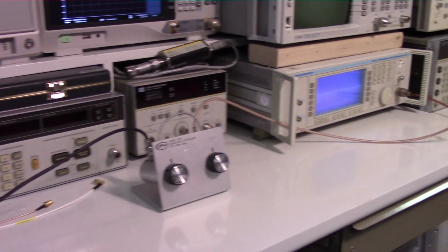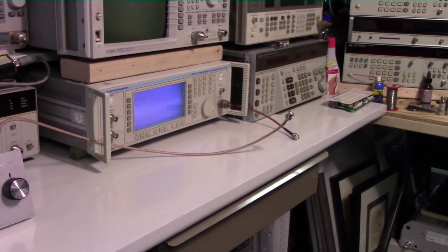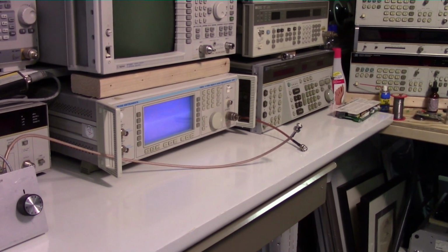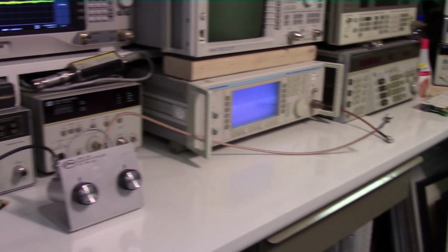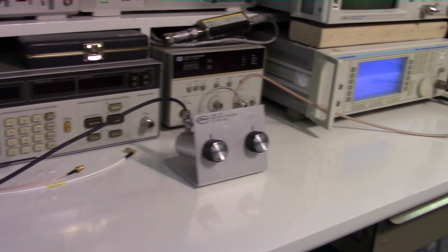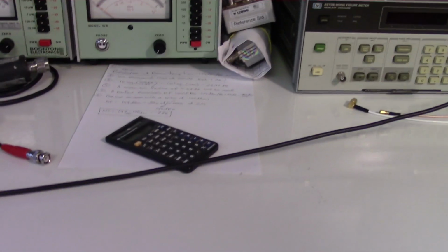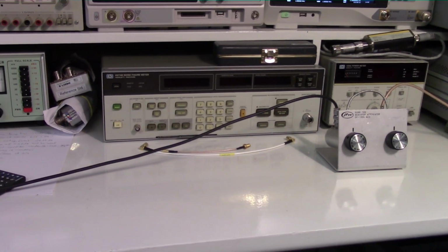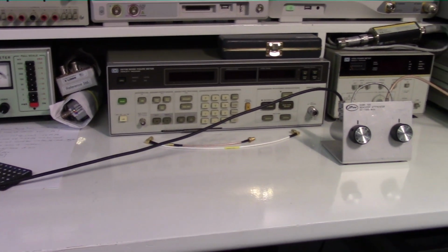One very, very final note is the cables that we use. Notice the way I've got this laid out. I had the output for the generator coming over here to the step attenuator, going over to this cable. Ideally, I could have put the receiver someplace over here so that I don't have to run a very long piece of coax.